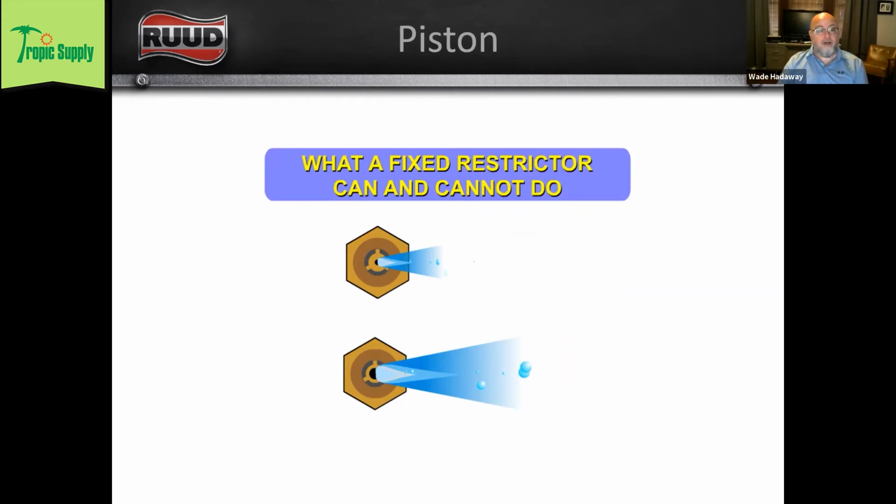It's very simple. For a long time, they worked great. They don't really allow us the ability to hit efficiency numbers that we need to hit in modern equipment. So that's why you don't see a lot of pistons out there. Are they out there? Yes. Is the industry moving more and more towards expansion valves? Yes.